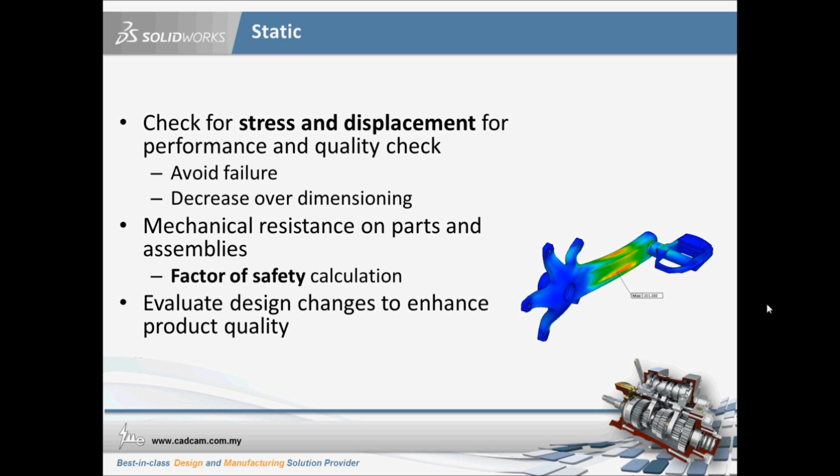Static analysis is to check for the stress and displacement, of course, to avoid failure and to decrease over-dimensioning. At the same time, you also will not forget that it can let us know the factor of safety of the design and give us more insight on how to improve the design.